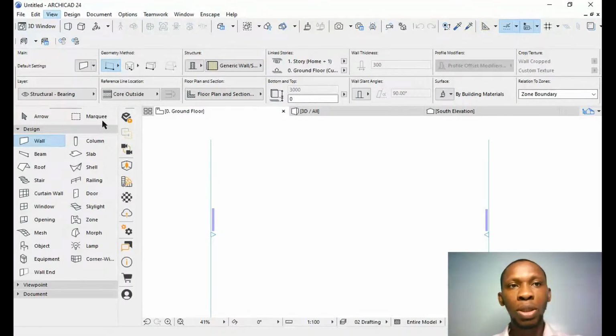Right, so we have guidelines, we have guideline options, we have surface snap. Surface snap, we most likely don't use altogether. We have grid snap. We don't use grid snap altogether because it helps that grid I displayed earlier; it begins to snap to a particular cross-section point of the grid, and then you can't draw out of the grid any longer. It is good if you want modular drawings, so that you have your drawings in 300 or more.